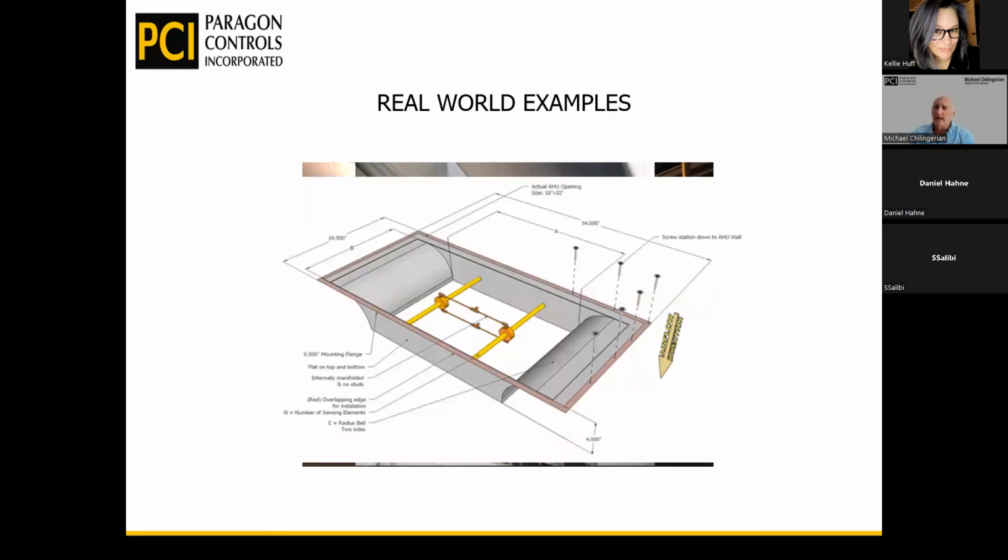Another item that we do, I'll show you a couple of different variations on this. In the real world, when you're measuring outside air, we want to keep the velocities up a little bit more. Even though we can measure down to 100 feet per minute, there's real world effects happening outside that can influence our airflow measurement. So what we found is that we want to try and keep a minimum amount of airflow at 180 feet per minute. By doing that, we find that we can measure better accuracy even at the low airflows.